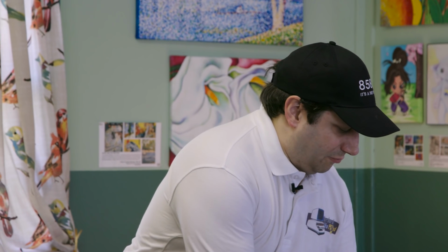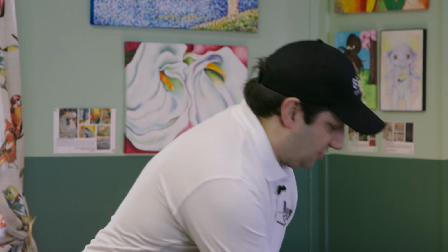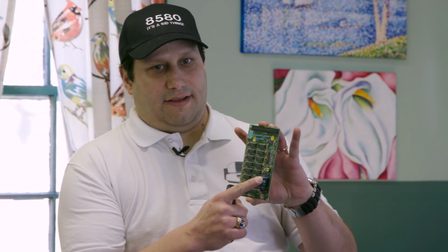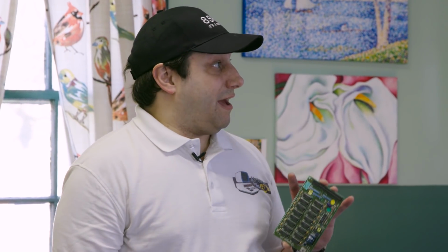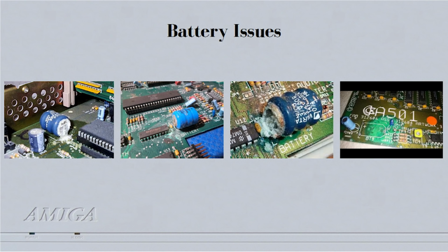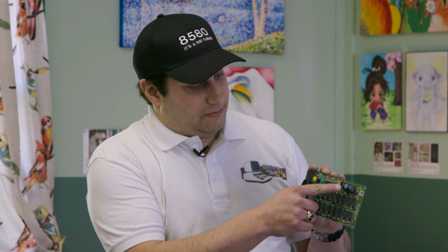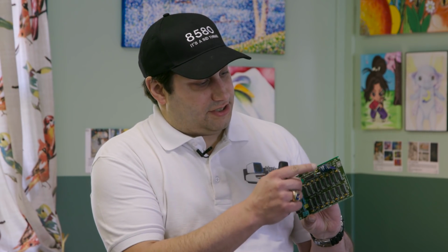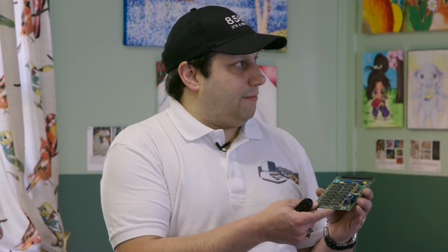And I actually have one. I only have one that's still attached to a board. That's this guy. These batteries do this after a while. So the most important thing when I get a machine is getting the battery off it. And I only haven't taken this one off because I can see it and I can keep cleaning it off. But you can see this one, there's that fuzz on one side. These will eat your motherboard, these will eat your traces.